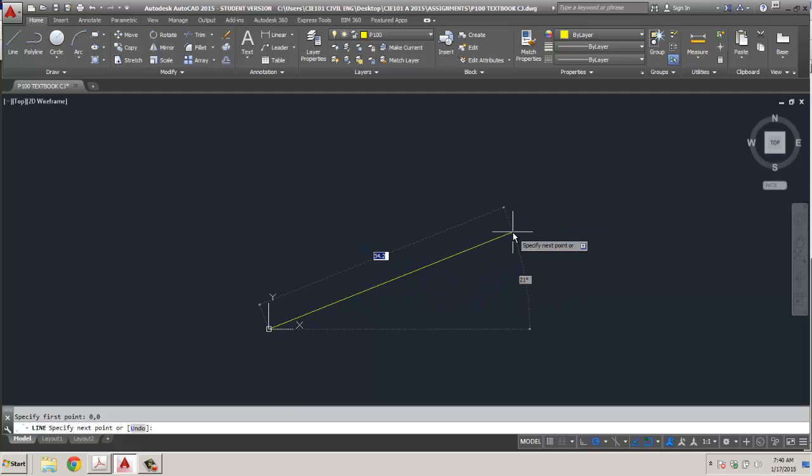Now we're going to type in our next command. We can just move our mouse. You'll notice it goes into polar mode automatically here. So we could type in a distance here. You'll notice it locks itself at that 0 for you, or it should. We're going to type in a distance of 8.5. Don't need to mess with the mouse or move your cursor in there. Just type in 8.5. Hit enter, because it's already at 0 degrees. And there's 8.5 locked in here.